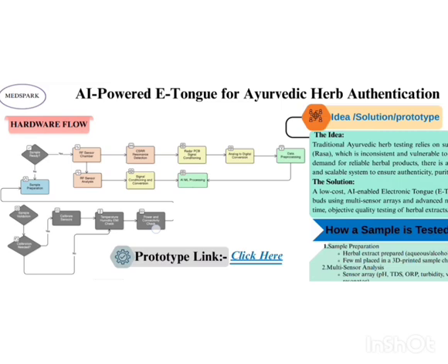The pH sensor is for checking pH, that is acidity or alkalinity. The TDS is for ionic concentrations. The ORP detects the redox potential. Turbidity detects the cloudiness or the opacity. The temperature sensor is for checking the temperature of the sample. The voltammetry measures the electrochemical response. Each generates digital signals. The RF resonator captures the dielectric taste fingerprints.